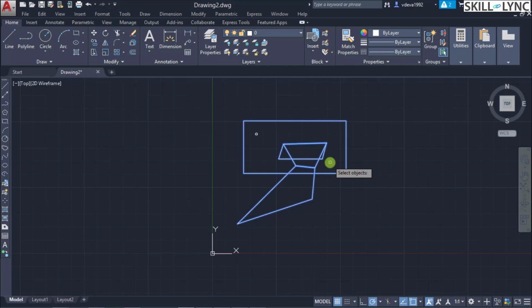So this type of selection is based upon the object or the feature, wherein you select the feature one by one. So where this selection command is of predominant use is if you want to do an editing operation on the given object, then you use the select command. So in certain commands, suppose you click on the move command, you are expected to select the objects here. So it means that this select command succeeds the move command.